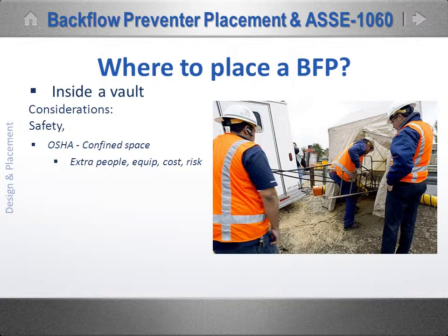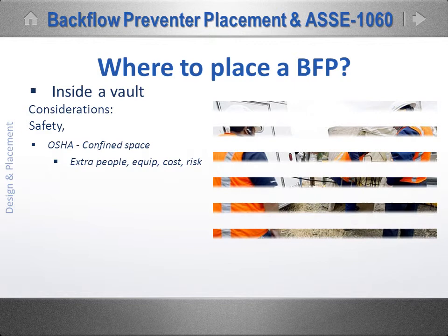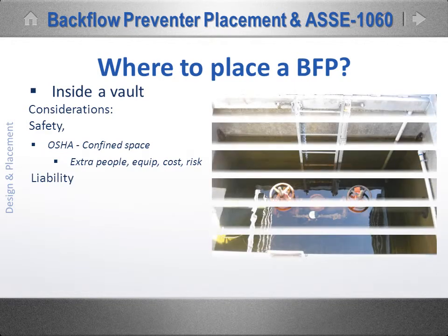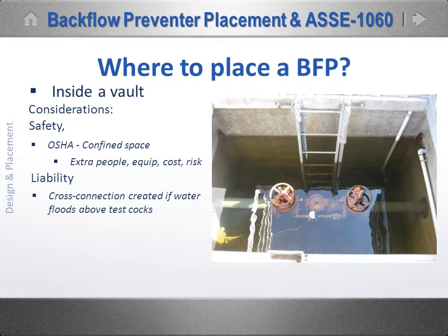But beyond the costs of safety for on-site workers, liability issues persist. When a vault floods like this one, the mandatory test cocks are submerged, and in that event, a violation of the International Plumbing Code has likely already occurred. The water may look clean, but consider what would typically make up the constituents of that water. Runoff of lawn chemicals alone make this a clear and present danger to the water supply.